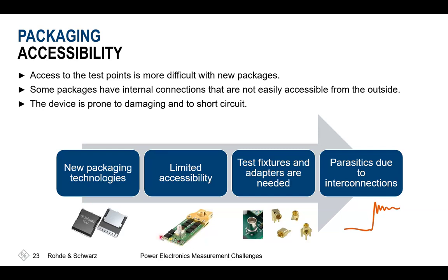Also, current measurements will maybe have to use a shunt resistor, or we'll need some structure which we could use as a coupling port. We'll have these connectors, even if they're MMCX. Those are quite bulky in comparison to these small, tiny semiconductor devices. And that's why measuring these signals clearly and having a good match to the initially expected values becomes tougher.